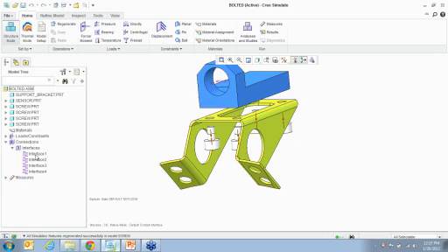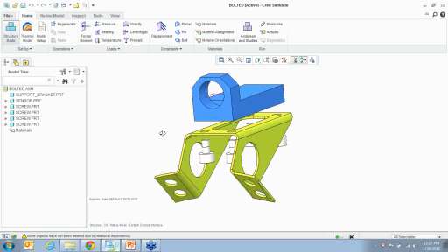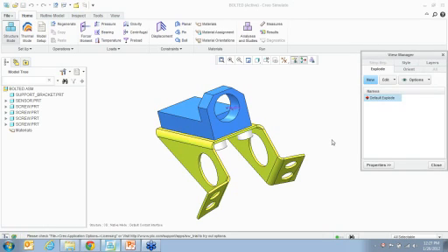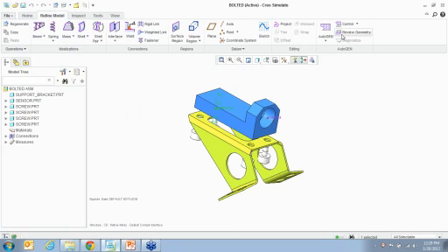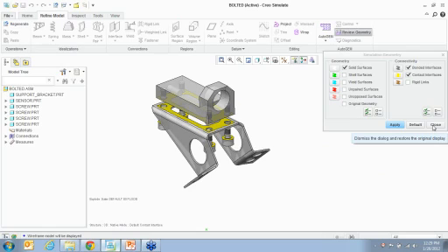All right. So notice that this assembly is more in an exploded state. I can go back and select the interface between the hole into which we work in the exploded state of the assembly. Also notice the Mechanica model setting to say everything is under contact. Those are your interfaces, and you can see in that gray individually contact to say bonded or free or whatever you want.